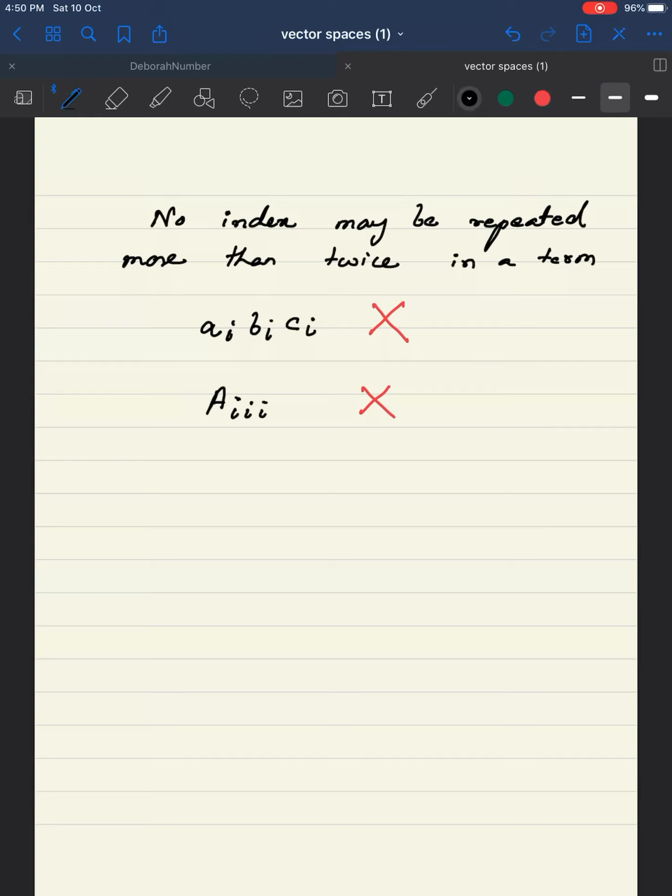Sometimes you might want to signify the actual value given by sigma_ii. So you might mean sigma_11, and what do you do in that case? If you have to suspend the summation convention, you can do it in two ways. Sometimes people just write "no sum," or sometimes underline the subscripts, and this basically means sigma_11 or sigma_22 or sigma_33 or sigma_nn, right?